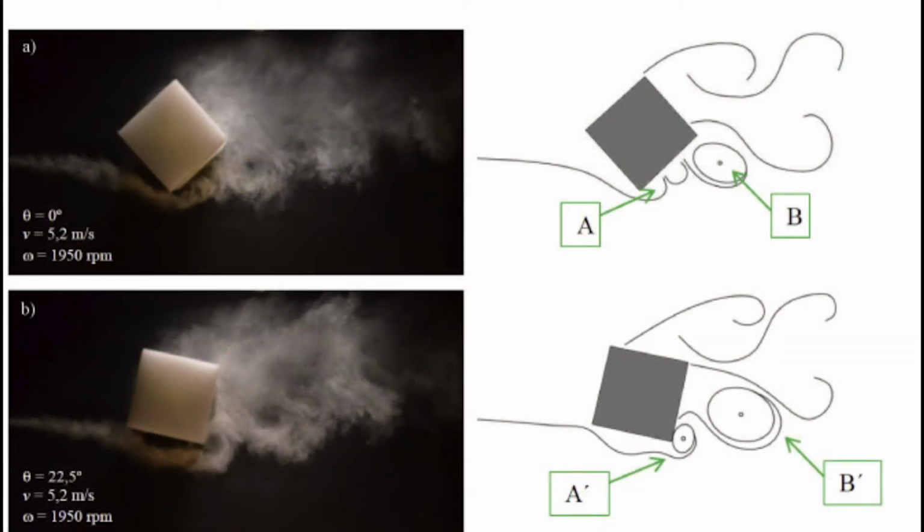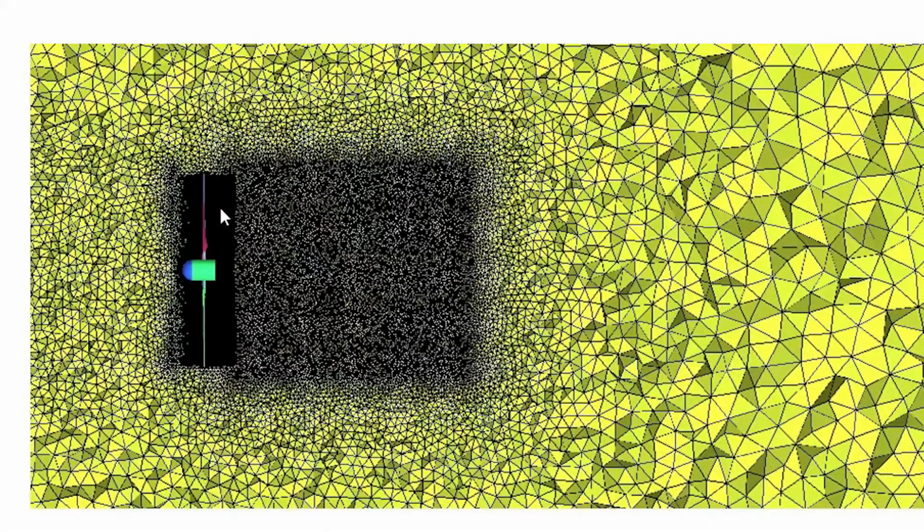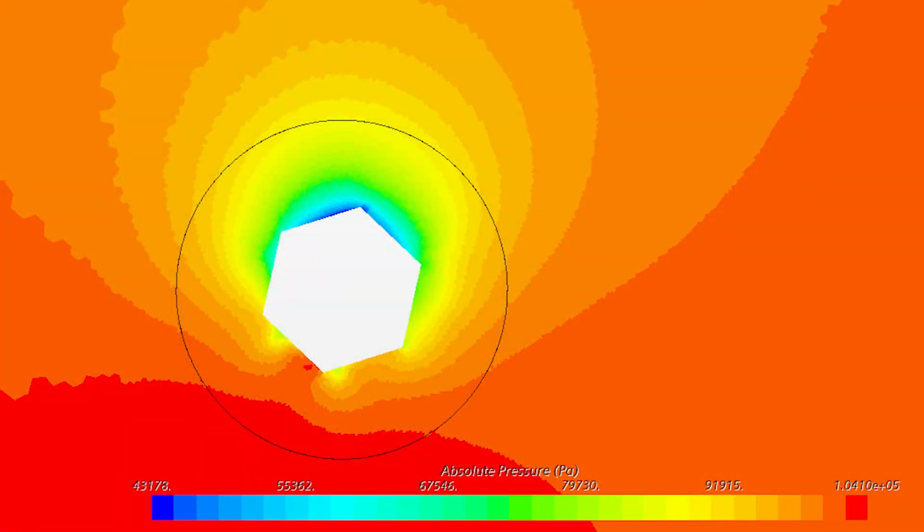To create more accurate simulations, experimentation with different physics values and flow fields would need to be explored. A constant density model was used for the water in the simulation to speed up the simulations. The Pezzati research was performed in air, which is highly compressible. Another improvement would be to increase the mesh density. Each simulation had roughly 45,000 elements, but this should be increased to 10 times that for ensured accuracy. While not perfect, the STAR-CCM+ simulations of Magnus lift are a valid model for the real world.